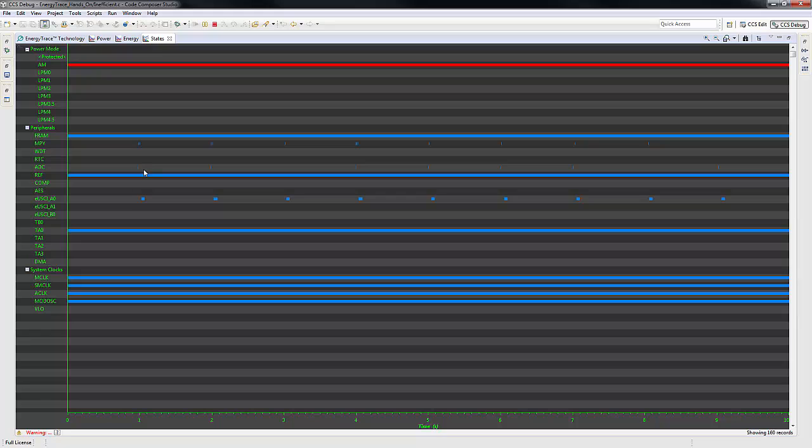You will see that the ADC kicked off some sample here, and the timer is the one that kicks the ADC to start sampling. So you see that my application is in active mode the whole entire time. FRAM is running. This is basically the worst possible scenario for an application that is not low power at all.